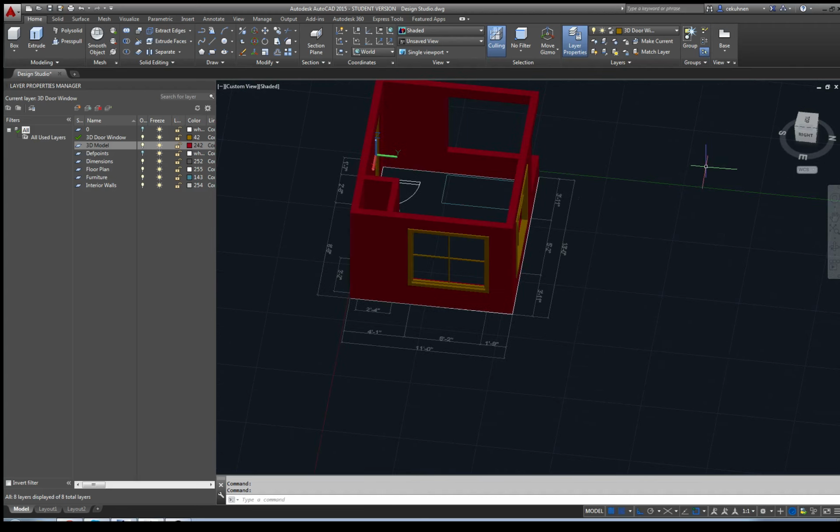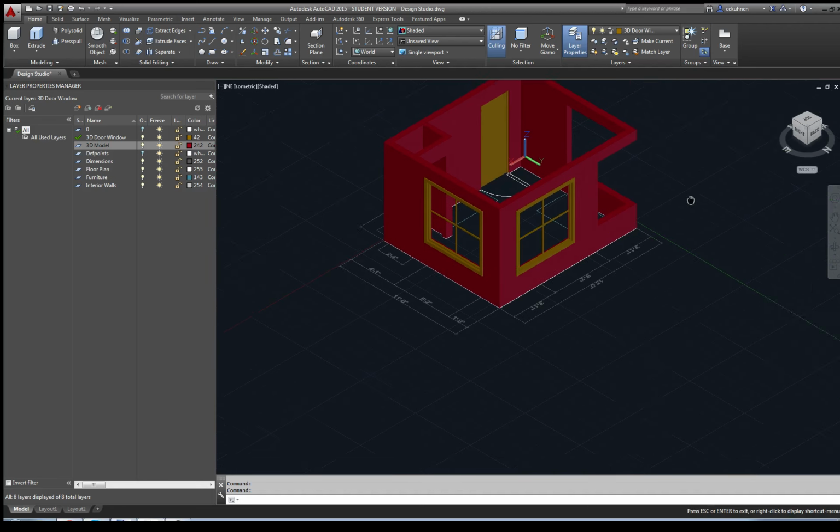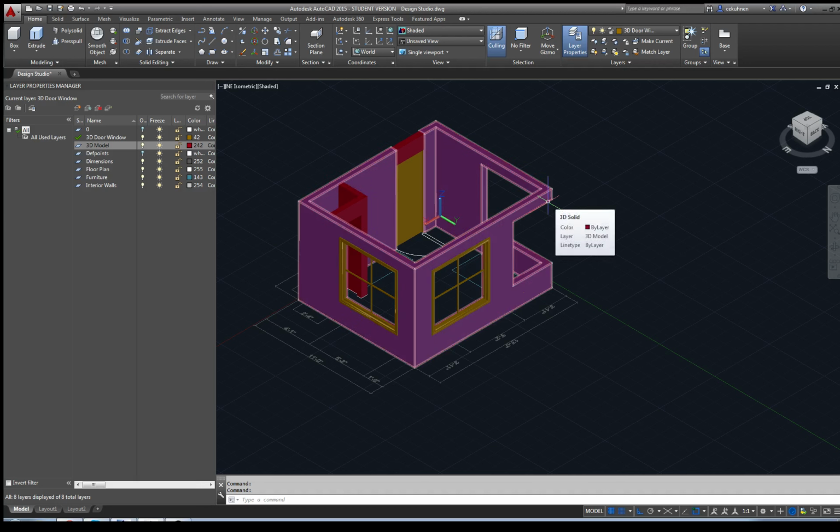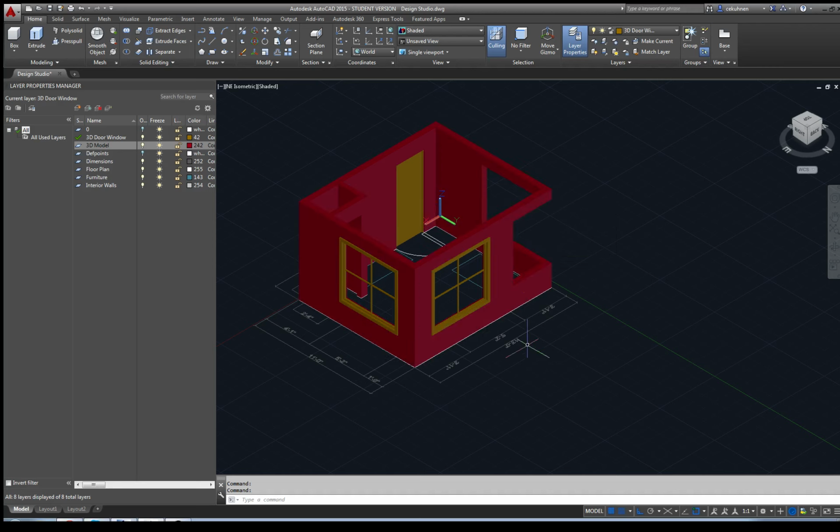So that basically was a quick demo in how to build kind of semi-interesting door frame and door and window elements. And you saw it doesn't really matter where and how you create them, because there are always multiple ways later to manipulate, to create, and then to rotate and position your geometry. And the 3D models are always nice to snap to and draw there, but sometimes it can get too complicated or confusing. So that's why it's good to measure parts and then, for example, draw something flat on the ground because it's easier, and then simply snap it into place.